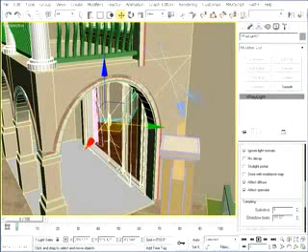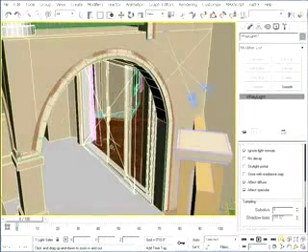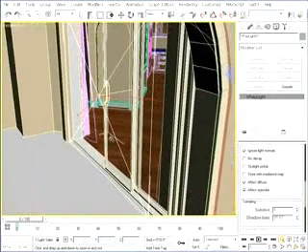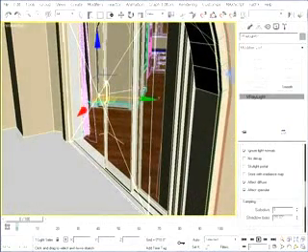And unlike the previous set of lights that I placed, this light is outside because the curtains inside the window, or inside the door opening, would interfere with the VRay light. The problem is not only am I wasting light because of the tinting of the glass, I'm also inducing more noise because the light has to go through this glass and also part of the curtains in order to strike the surfaces inside the living room. I can improve the render settings, which of course means greater render times, but if there's any way I can get away with placing this light inside the room, then I always will.